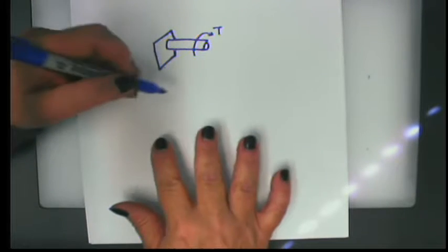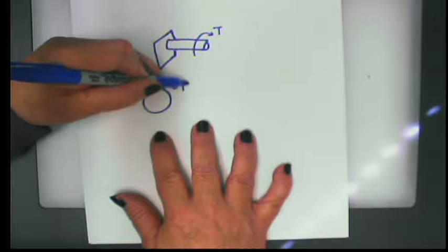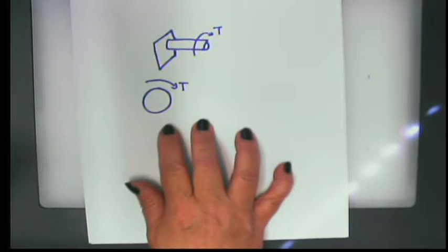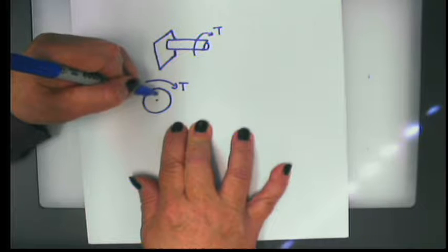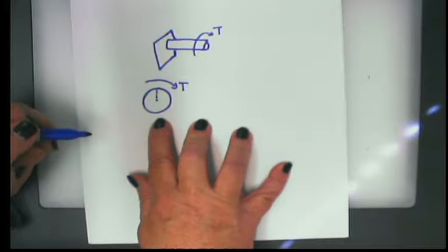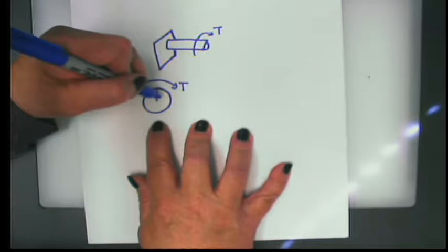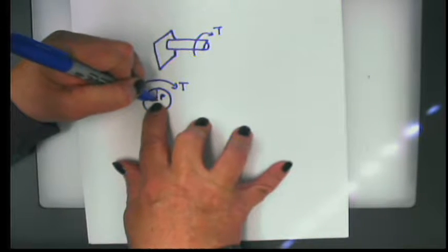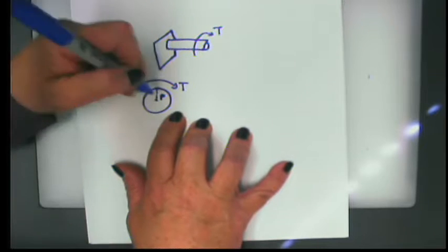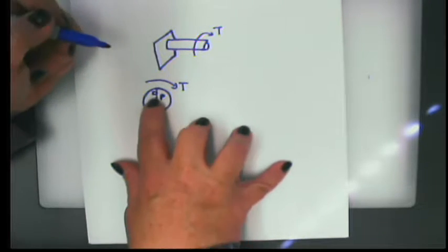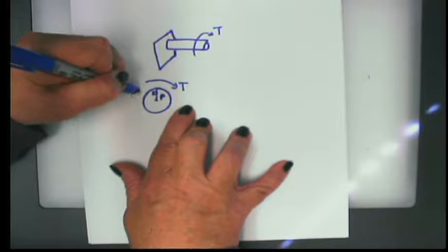torque. Right. So the first thing we do is we define the geometry, and on the cross-section, when we have this torque applied to it, we consider that at the center of the circle, the center of the cross-section, no movement occurs. But as we go up to the distance of the radius, which along the radius we're going to call the distance rho, as rho increases from 0 to r, the radius of our particular circle, we can look at a finite element and recognize that it's being subjected to some force, which we would call, since it's an element, dF.